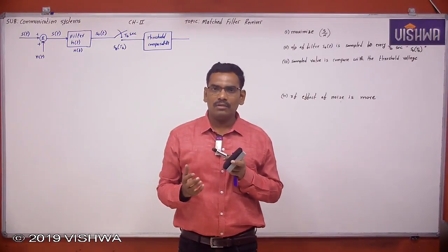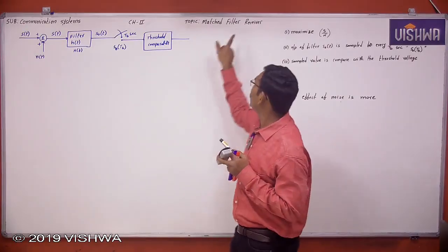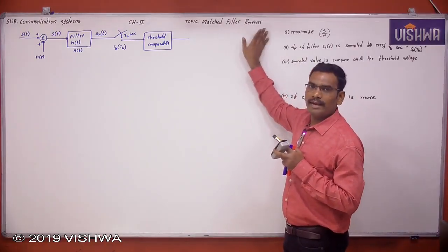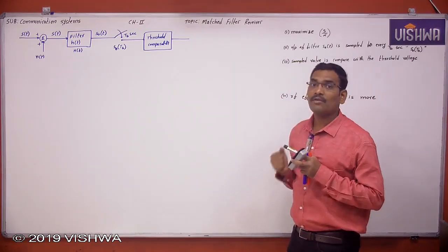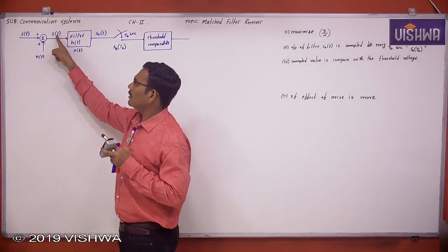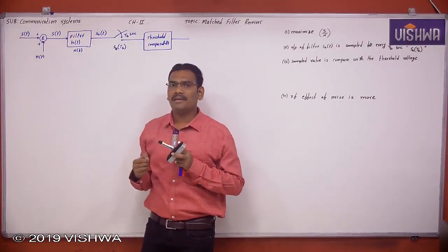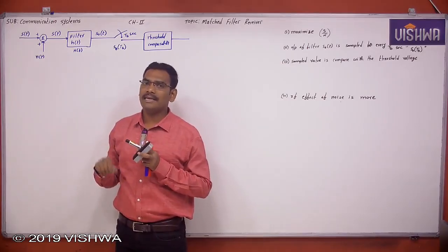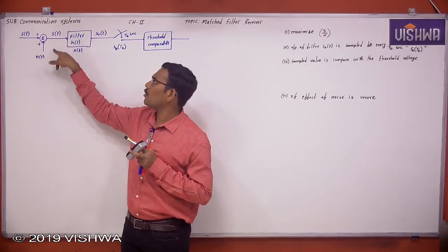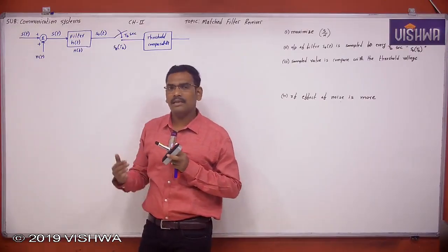Okay. So at the receiver input, now what I am using is a filter. Forget about match. Now receiver is clear. Now I just come to the word filter. So at the receiver, I put a filter. For what purpose, sir? Now this filter input is not only a signal, the signal is added with noise, am I not? One of the properties of thermal noise is that it is additive in nature, always added to the signal. So this is a noise affected signal, having some signal to noise ratio, am I not?